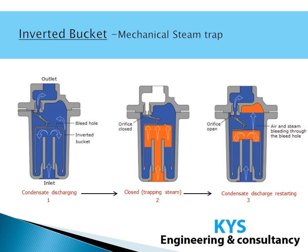The air entering at startup will also give buoyancy to the bucket and close the valve, but the bleed hole then discharges the air into the top of the trap body, and thus the bucket comes down and opens the valve. Air is then finally discharged through the main valve. So this is in brief how this inverted bucket steam trap works.